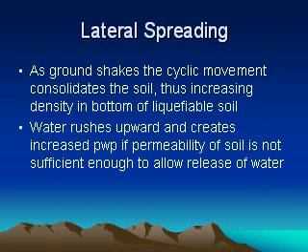As the soil shakes, it causes the soil to consolidate. The bottom of the soil increases in density, and the water that was filling those voids rushes upward. If the soil's permeability is not sufficient to allow that water to dissipate fast enough, you get increased pore water pressures. If the pore water pressure increases above the static strength of the soil, that's when you'll get liquefaction to occur.